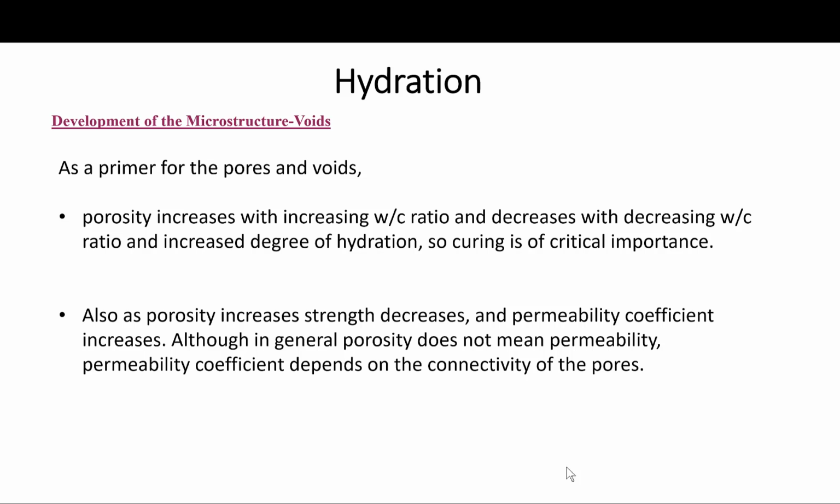Also, as porosity increases, strength decreases, and the permeability coefficient also increases. We will talk about permeability in a bit. Although in general, porosity does not mean permeability, the permeability coefficient depends on the connectivity of the pores, not just the presence of the pores. So there is a distinction between porosity and permeability.